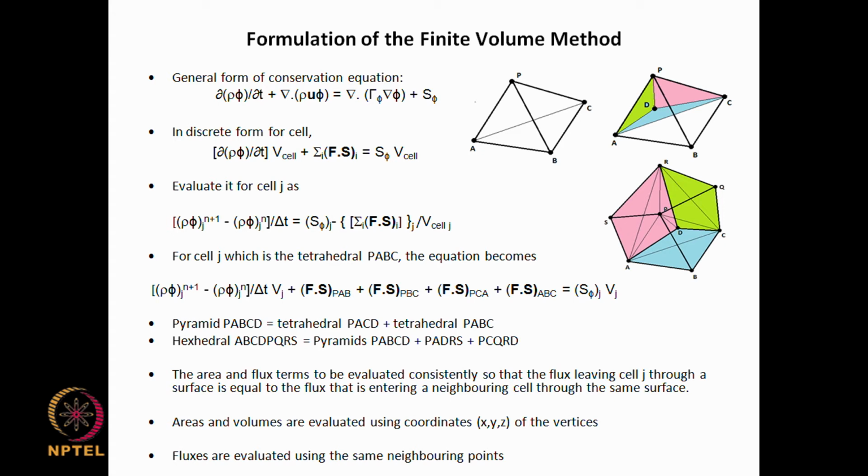So, we will be able to convert this equation into something like A phi equal to B. All it now requires is how to find these vertices, okay, how to divide the control volume into a small number of bricks of this kind of planar and hexahedral shapes. So that is part of the grid generation.